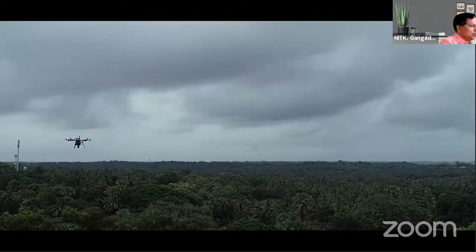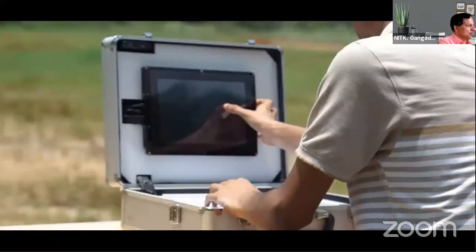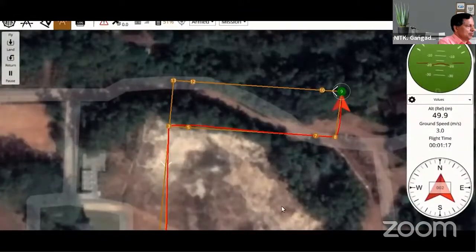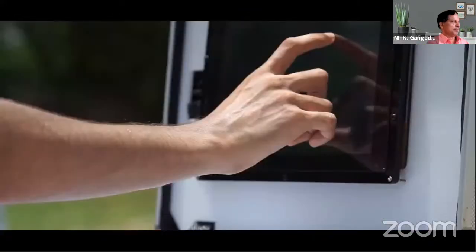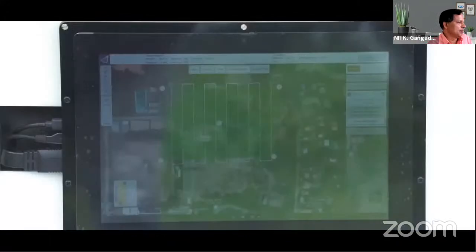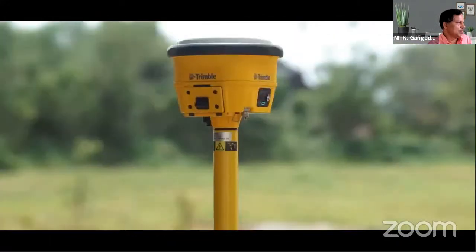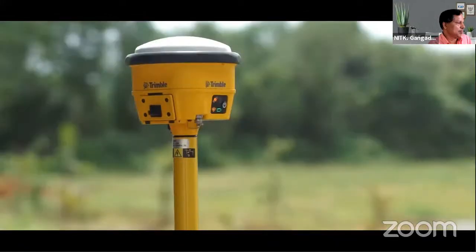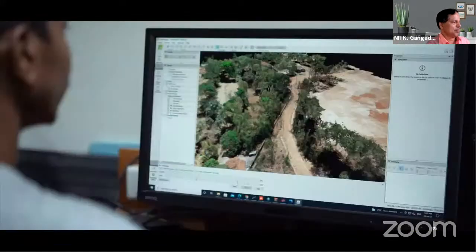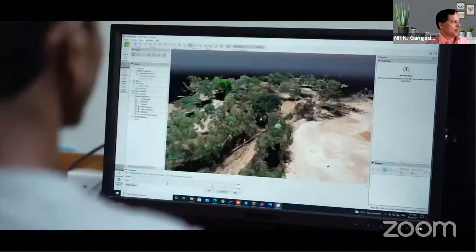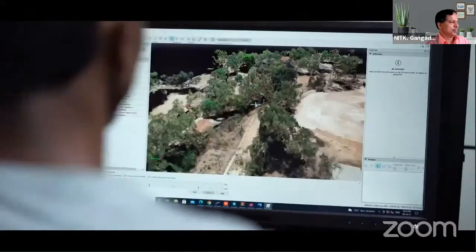Using the ground control station, the waypoints are created over which the drone has to fly. Monitoring of all the required sensors, drone health, ongoing flight progress, and GPS GNSS connection is done with the GCS. LIDAR and photogrammetry devices are merged together so as to get highly accurate and precise data.